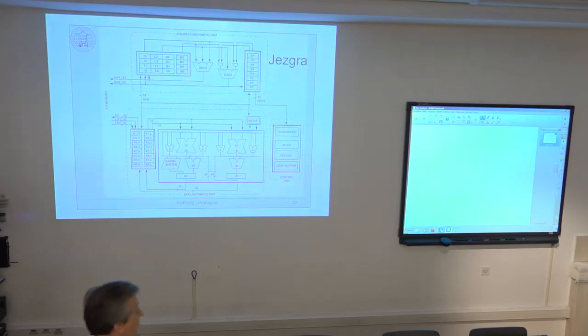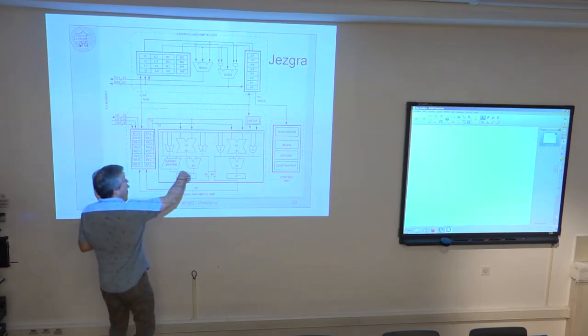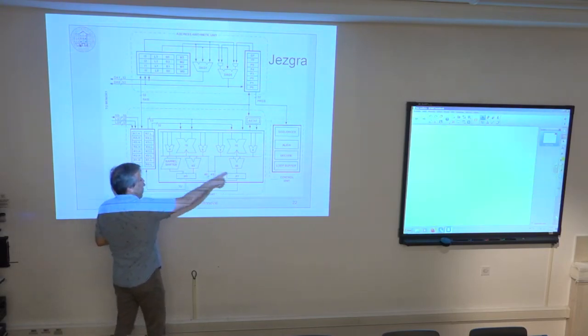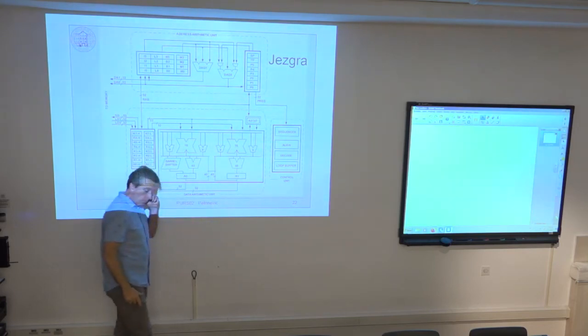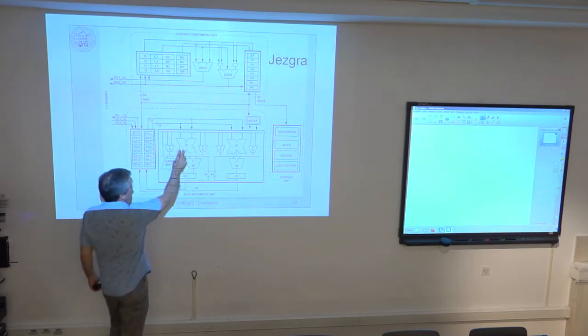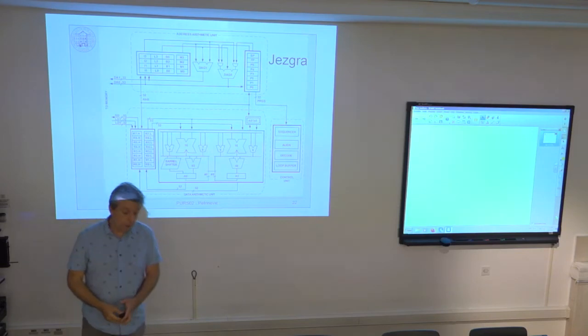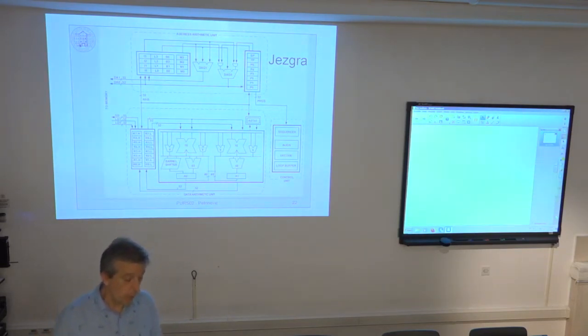So 32-bit for result lower word and upper word, and finally 8-bit extension, altogether 40-bit, that can be accumulated in this accumulator as well as in this accumulator. The difference is that you don't have input registers. With the simple architecture, you have the dedicated X branch and Y branch input registers for the multiplier, MX01, MY01. They are absent here. I don't have them here.